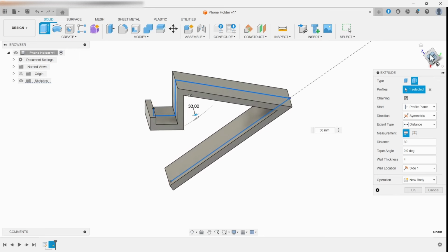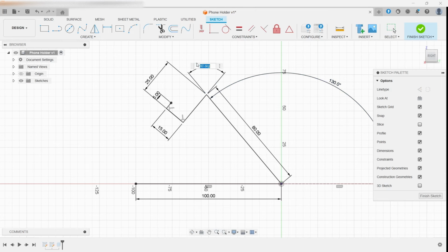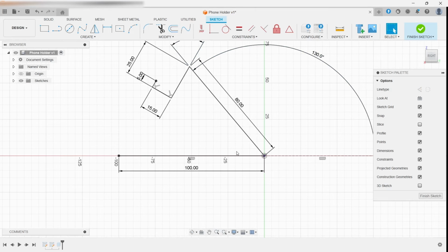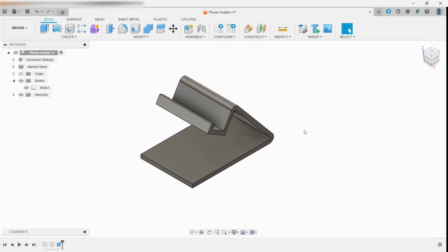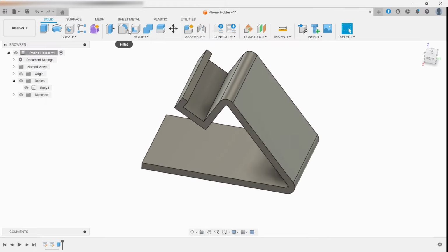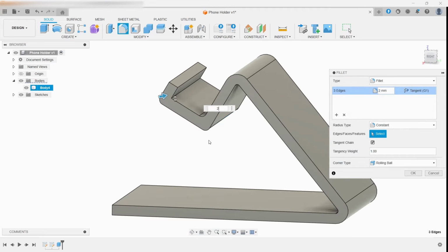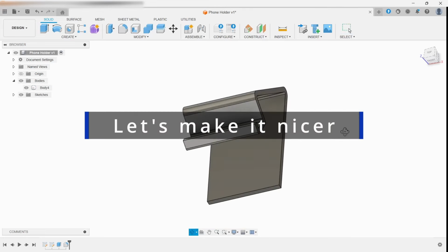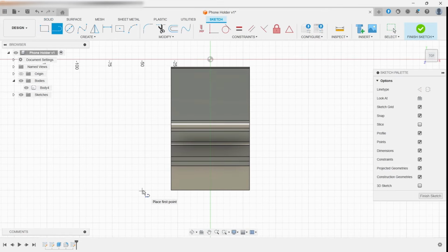In this case, we can choose a thickness of say 4 millimeters, since that's a good common ground between having something thin and something a bit thicker. Now, to avoid doing some fillets after, you can always just change the sketch and then update the extrude. To actually change a surface after it has been extruded, you can use the fillet tool. This pretty much just allows you to make a rounded corner.